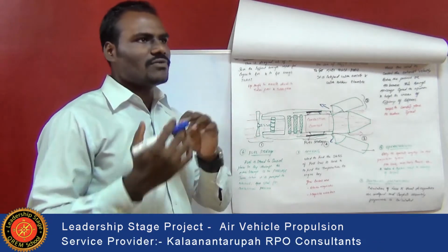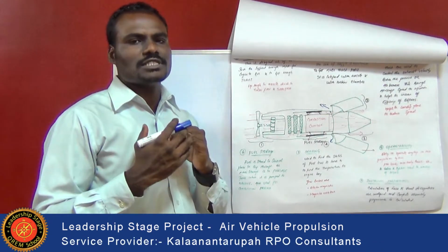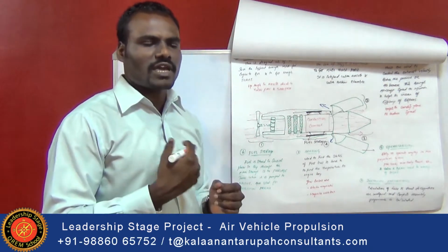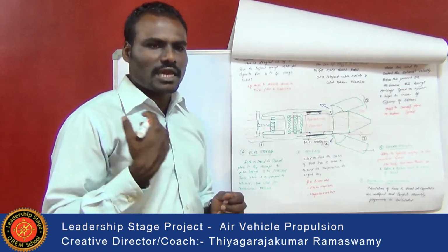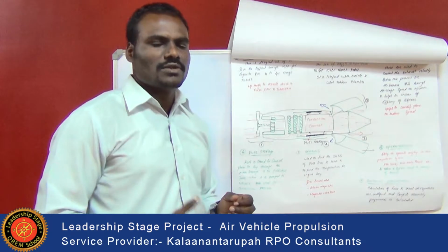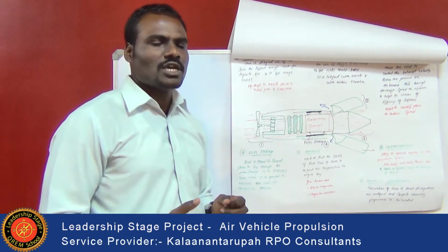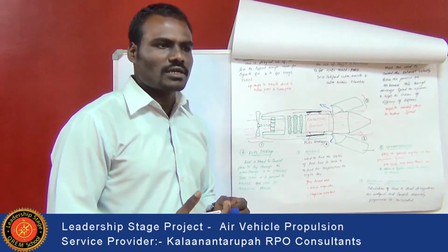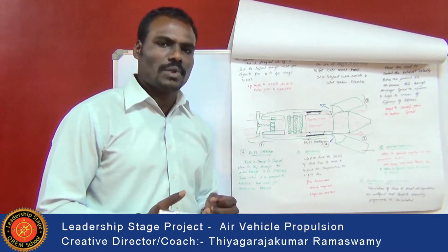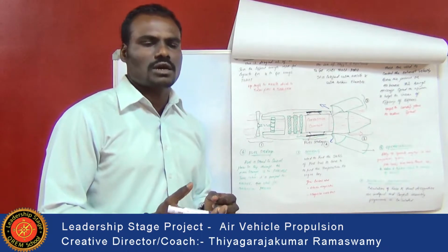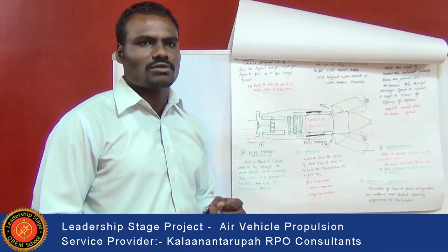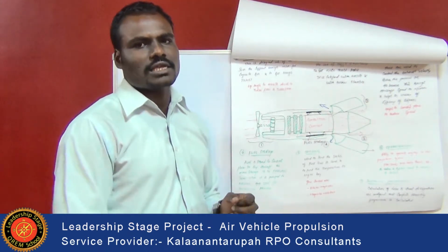From the wing, it is subjected to the engine with different kinds of pipelines, and wherever the fuel requirement is there, there will be a pipeline, and it is being pumped with different pumps and hydraulic and pneumatic systems, so that different blocks will be placed, or different controls or valves will be controlling the fuel system in order to supply the fuel to the aircraft.